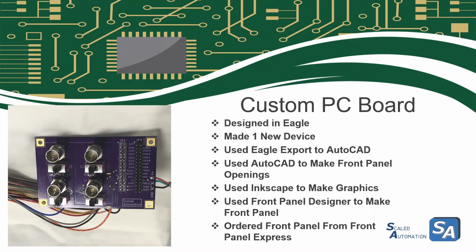So AutoCAD is extremely precise. And then I used that file that was in AutoCAD to make the front panel openings. So the devices themselves are not the openings, but I used AutoCAD to put openings where those devices were. So holes for the BNC connectors, kind of rectangular openings for the switches, another rectangular opening with a little cutout for the logic analyzer connector, and a few others that you'll see. And so I did all that in AutoCAD, and then took that AutoCAD DXF and put it into Front Panel Designer to actually make the front panel.